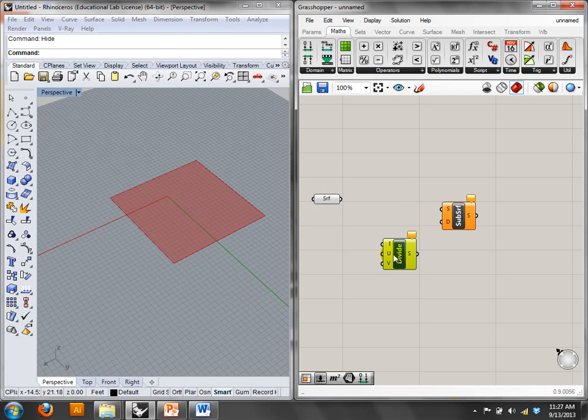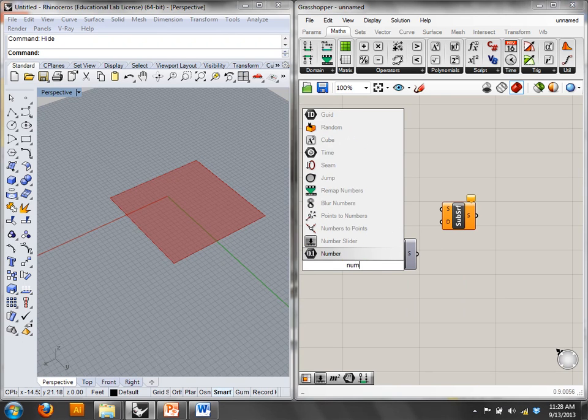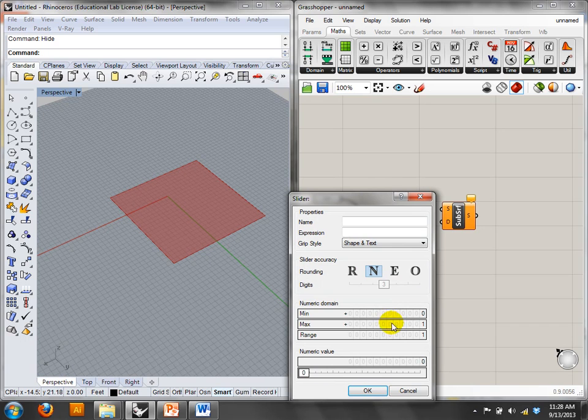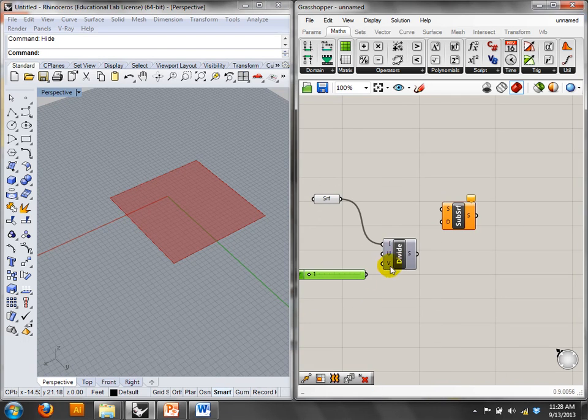Okay, so this one, divide domain squared. Just type in divide. It starts with some base domain, which we're going to get from the surface. And then we have these UV segments, and UVs will take a number slider. It basically tells us how many pieces we want, like how many ways do you want me to cut this up? Okay? I'll just do these as from 1 to 20. Use whole numbers, no fractions of things. You can't have a fraction here.